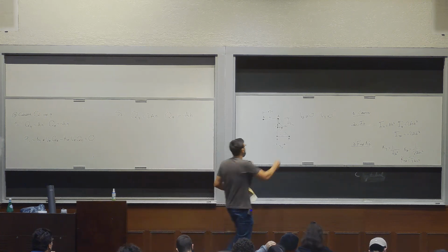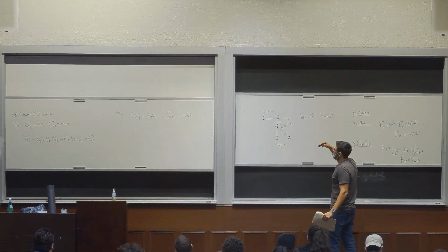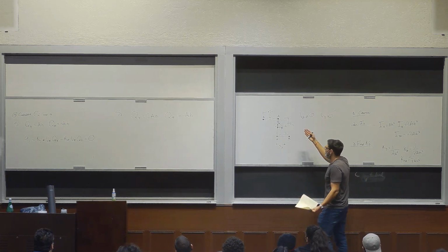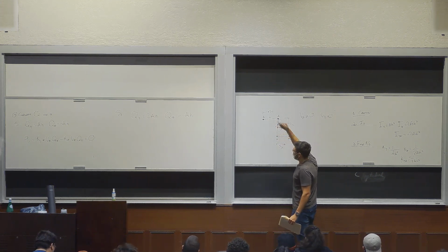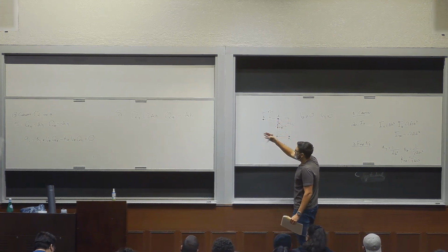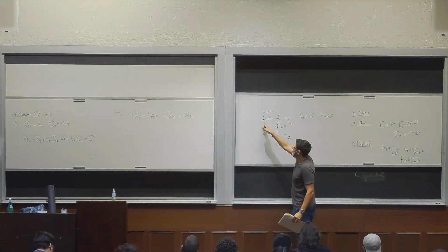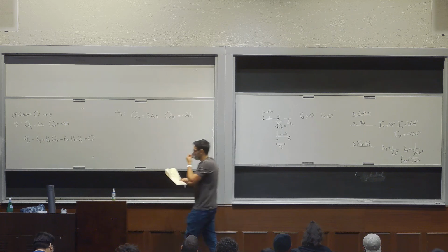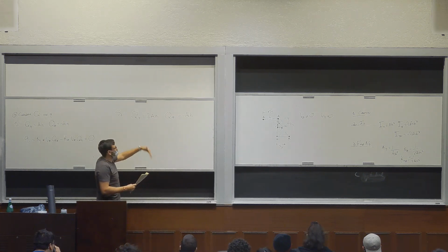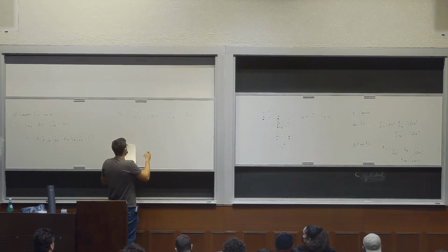All right, so you're making a cut here, let's say at any arbitrary position S2, and you're going to add the relevant areas that are above that line, before that line. So there's two A's here, and the centroid is at H. And then for QZ, the Y position of the centroid for this one is 0, so you can neglect that one, so you're still only left with this one being the relevant one. So you got that. You can see it's a lot easier now, right? You don't have to do these linear equations and stuff, so it's a lot easier.